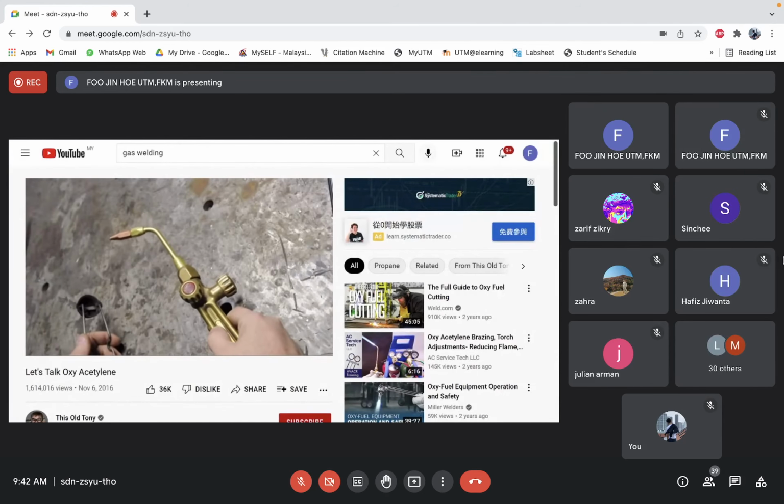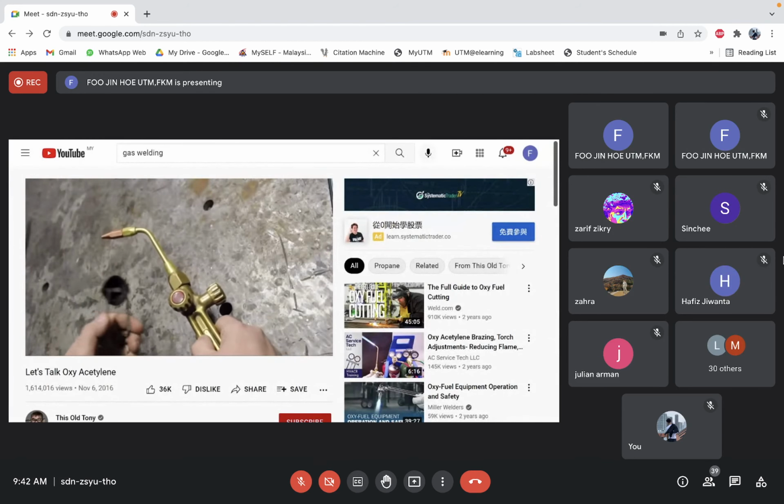The only thing I've ever been able to think of is maybe the torch pressure could blow out your open flame. Like you try to light your torch with your lighter, and it just blows the lighter out like a birthday candle. Then you might be in a situation where your torch is putting out a deadly mix of acetylene and oxygen, and you're trying to strike your lighter back up. Anyway, I'm going to light just the acetylene.